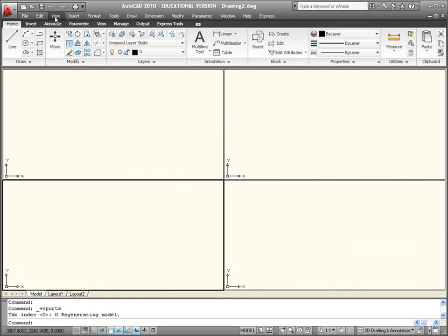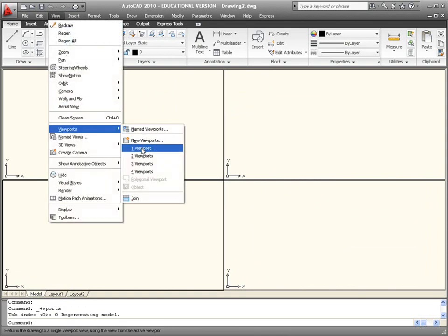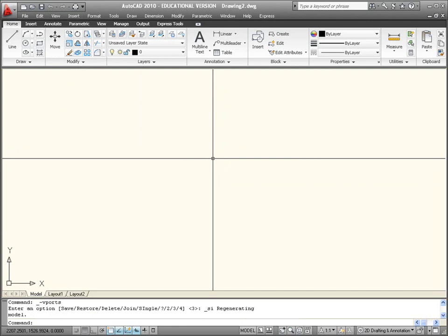would you bother splitting up the screen size? I mean, it's small enough, and you buy a large monitor and then you go make the drawing area smaller again by tiling the viewports in model space. Now in model space all viewports can only be tiled, so one on top of the other. You can't change shapes or anything like that. You can't make up your own little shapes of viewports, and they're kind of stuck one on top of the